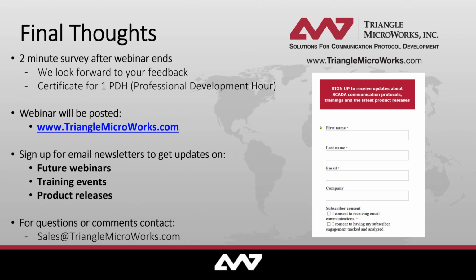But sometimes two logical nodes will be using the same GOOSE signal, or for other reasons, they might be placed in LLN0. And that's really where the source refs come in. I wouldn't say it's the primary reason that source refs exist, but it's one of the primary benefits from a simulation perspective. We now know in the substation section which L node was intended to receive that message, and we now know where the XREF lives that implemented that specific connection or input, and therefore we're able to make that connection automatically if the source ref is present and configured.